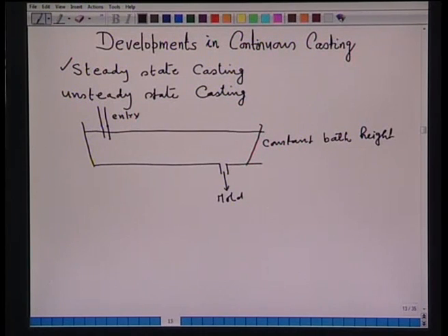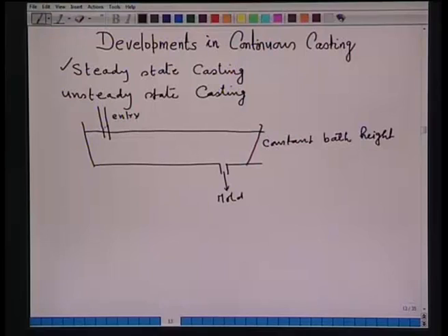Now, I have said that in order to use the Tundish other than its transfer function, that is, for example, removal of inclusions, mixing, distribution, it is required to modify the flow pattern in the Tundish. What I mean by the flow pattern is that as the steel enters from the ladle, that is somewhere here, steel is entering and it is exiting somewhere here. So, that time which I have said as a residence time is a very, very important time. Now, how the steel flows when it enters and when it exits, that is very important.